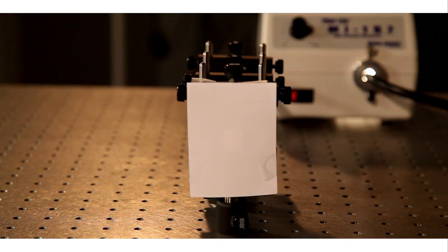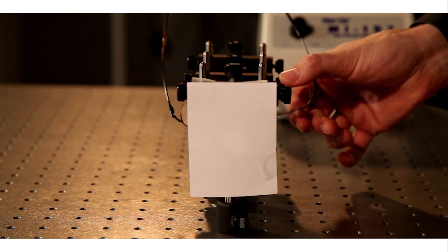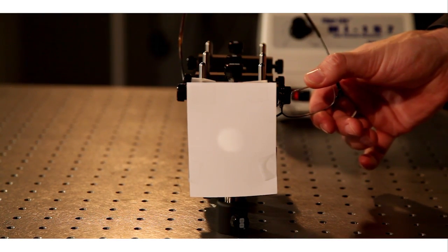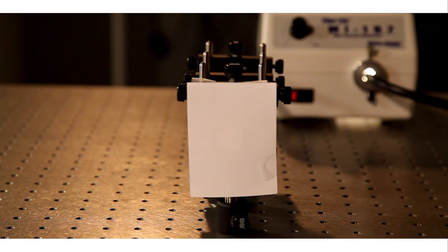Additionally, we showed how we can use a pair of polarizers to see stress in a material, such as a pair of eyeglasses. Why did this work? Stress in a material causes birefringence and will change the polarization state of light as it travels through an object. Since we know that we should effectively block all light between two crossed polarizers, we know that stress in the object has caused the change.